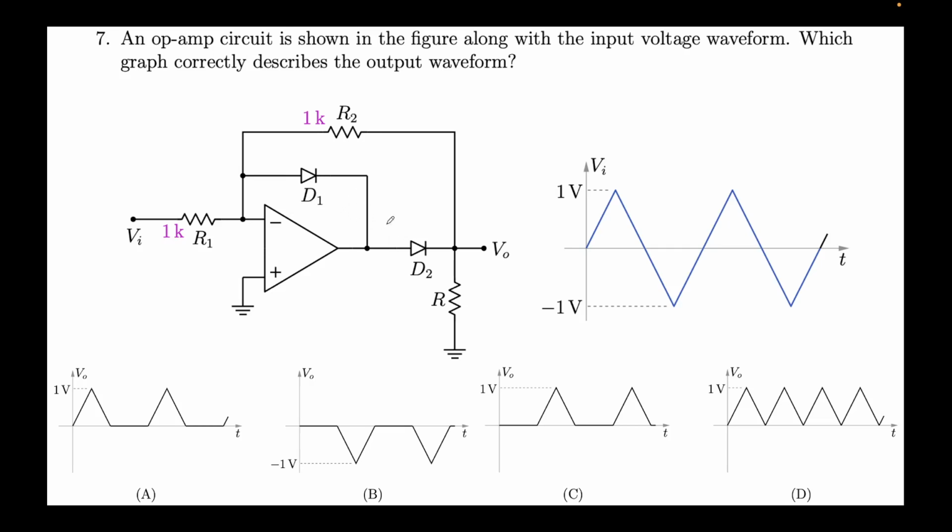So we'll assume the diodes to be semi-ideal, which means that their characteristics, by that I mean ID versus VD, are of the form of this. So I assume they turn on at 0.7 volts, and for negative bias I am assuming they have 0 current, while they turn on only at 0.7 volts. This is true for D1 as well as D2.